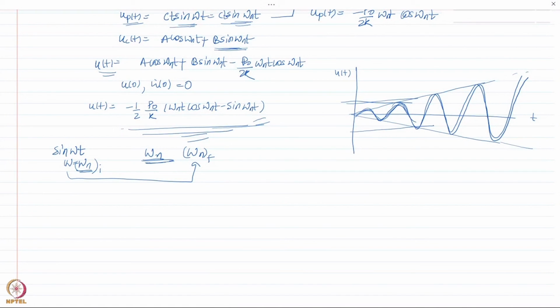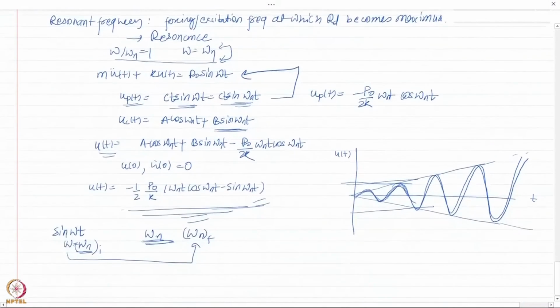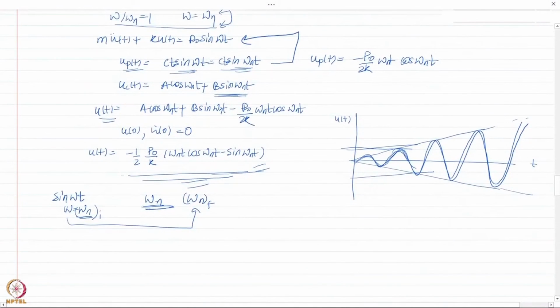Another situation could be if it's not brittle, but very ductile, for example a steel building or some steel structure, then it would yield at a certain point. So again, the stiffness would change, and the natural frequency would no longer be equal to the applied frequency. Then the system would come out of resonance, and again we can go back to the original solution.